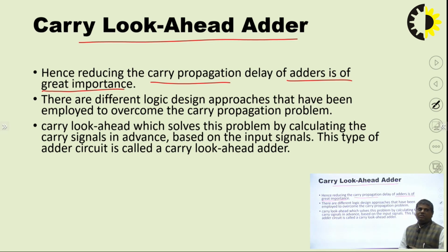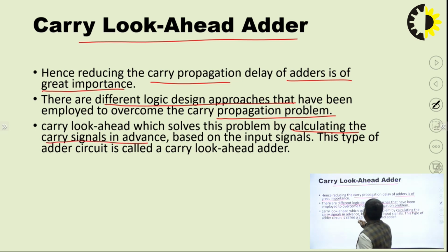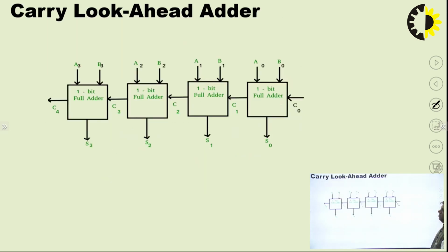There are different logic design approaches that we have to employ to overcome the carry propagation delay problem. The carry look ahead adder solves the problem by calculating the carry signals in advance. Now, with the help of the circuit diagram, I explain what different types of delay occur and how we can calculate the advance carry.